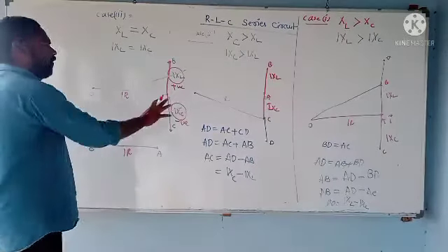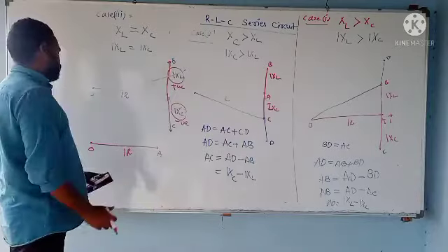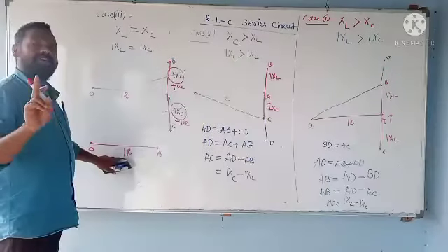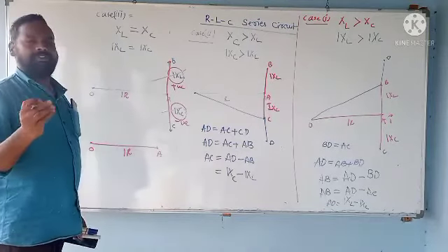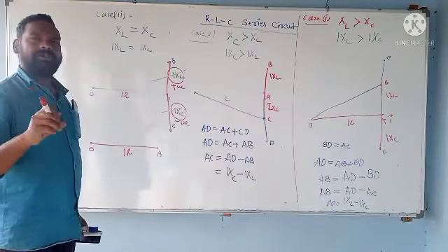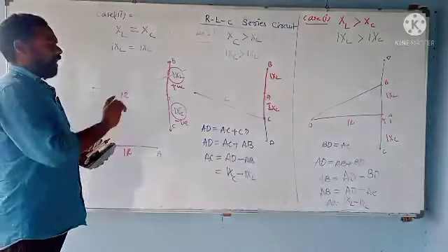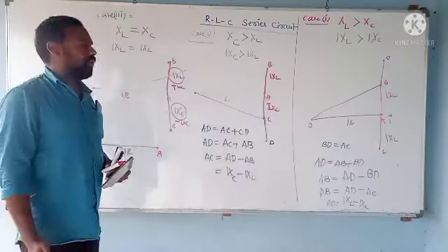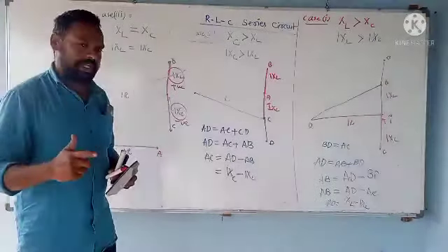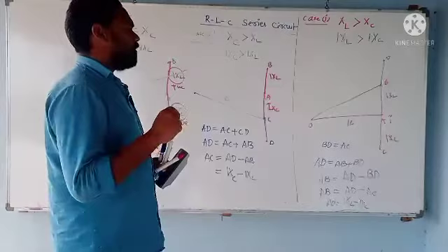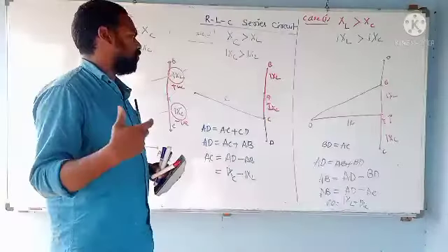So anyhow, whether you are taking resistance, inductance or capacitance, definitely that will be a combination with resistance, because you should understand that resistance will definitely be there. Whenever you are using conductors, they definitely offer a finite amount of resistance. So if the inductance value is higher than the capacitance, then that circuit is going to behave like an inductive circuit. Whenever capacitance is dominating inductance, then it will behave like a capacitive network.